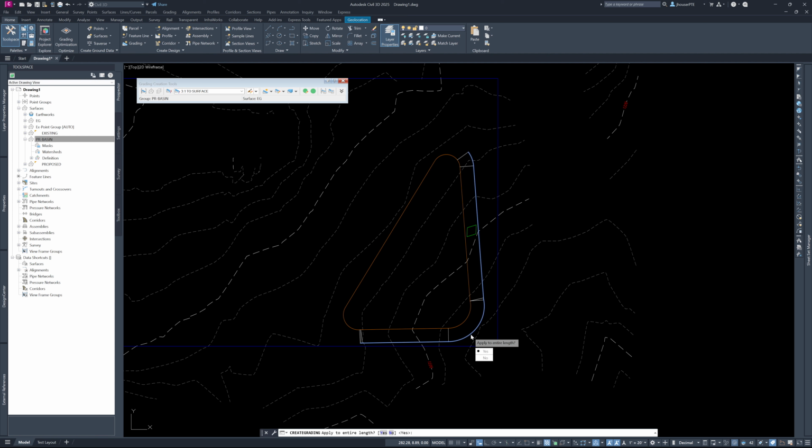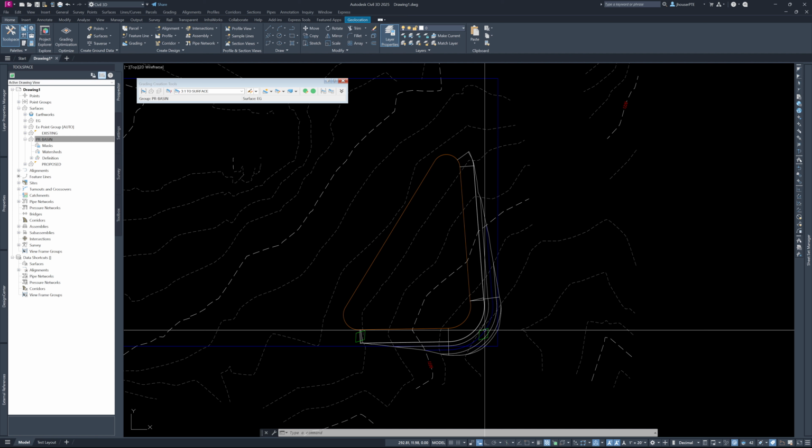It's going to verify what your slope is, 3:1. You can just right click on that. And if there's any fill slope, it's also 3:1. And what you'll see is that, hey, there's our contours we're looking for. Now I hit escape to get out of that command, and you'll see, hey, we got a diamond here, and now we have a diamond here because we have two individual grading objects, but they are linked to each other.